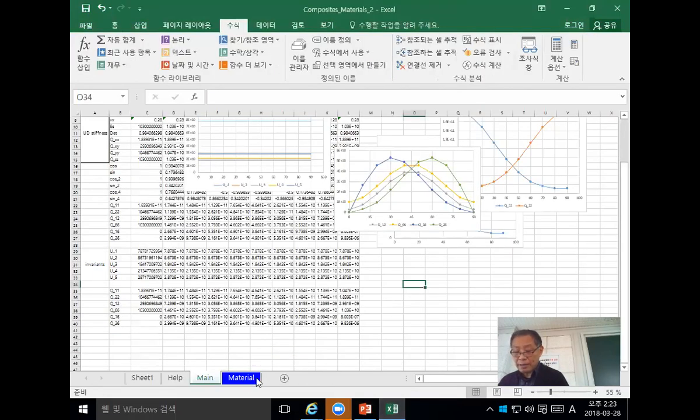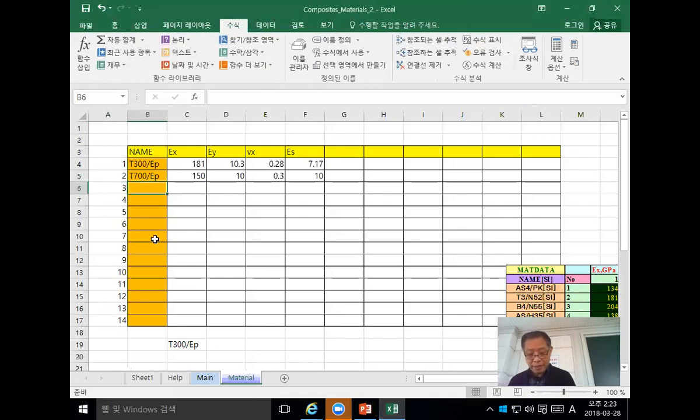You can expect that, say here, aluminum. What is the E_x? Well, about 70 gigapascal. Poisson's ratio is about 0.3. And now the important point is the shear modulus. What is that? One plus... We know this relation for isotropic material, right? Okay, so that is the third material.